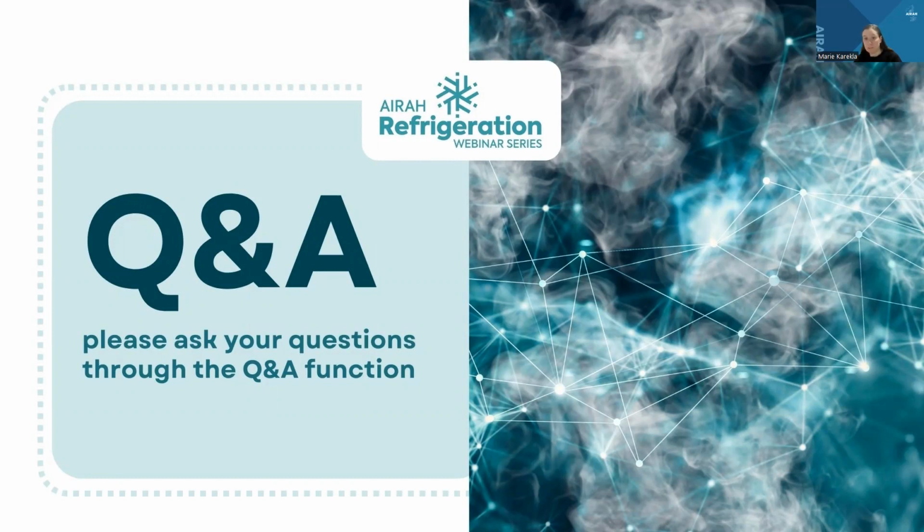Yeah, sure. Another question here is: do cool rooms have a safety latch on the door to prevent persons from being locked inside? Well, if you look at the standard, there's a requirement so that nobody can be locked in there. Whatever mechanism you use, it could have a padlock outside, but internally the mechanism should be able to be dismantled to open the door.